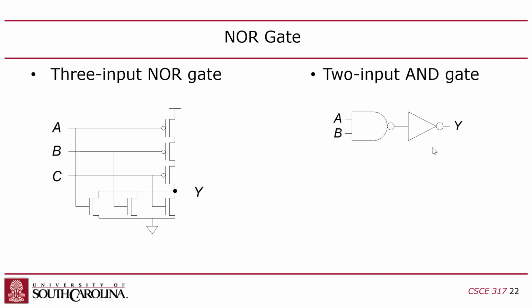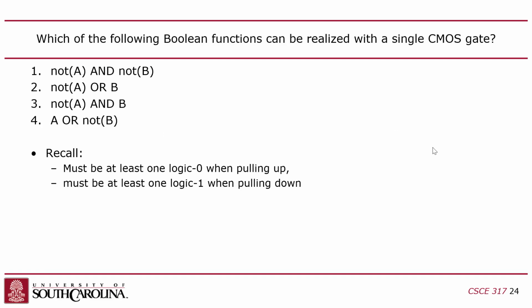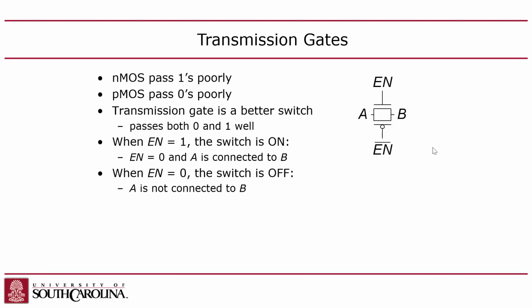Likewise, an OR gate works the same way. If you put all zeros into an OR gate, its output is 0, right? But that's impossible because if I have all zeros, I can't activate any of my NMOS transistors, right? So if you want to create a positive logic gate like an AND or an OR, you have to basically build two gates in series and connect them. You can create a NAND and then an inverter separately, and then you effectively have an AND gate there, but it's 2 gates, it's not 1 gate. Okay, so let's see, I think that's about how far we got last time.